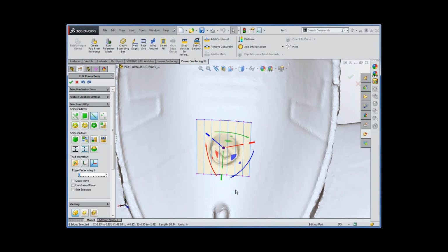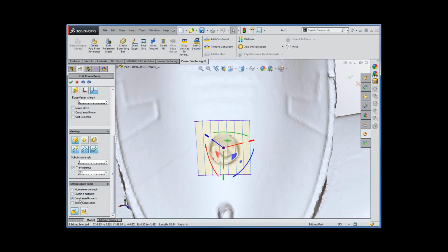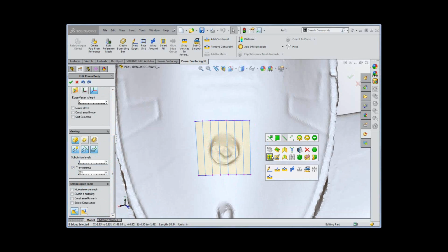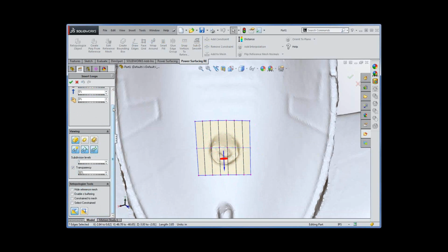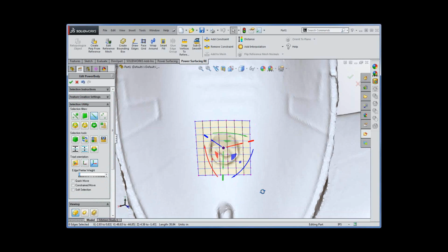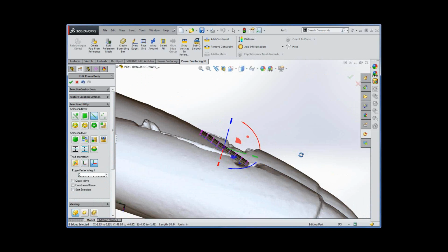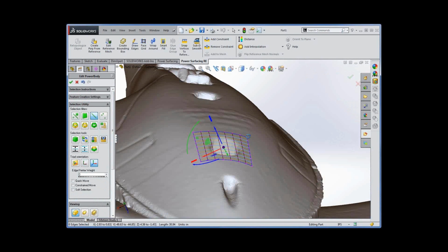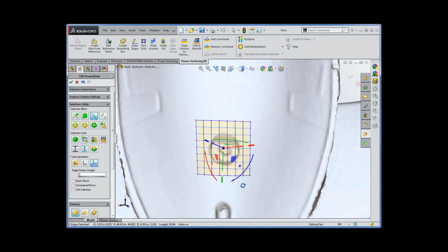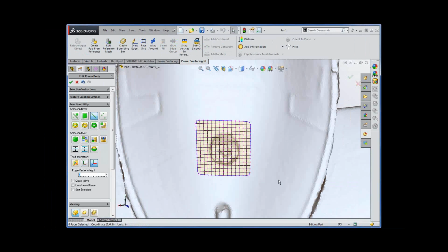So I'm going to cancel this. And what we want to do here is go down and turn off the constrain to mesh mode. So that's off now. Now I can go in and add my edges the other direction, like so. And they're not getting snapped, so they're kind of straight across. If we look here, you can see them kind of going like that. And now, before we reconstrain, I'm going to bump up the resolution on this and subdivide it once.